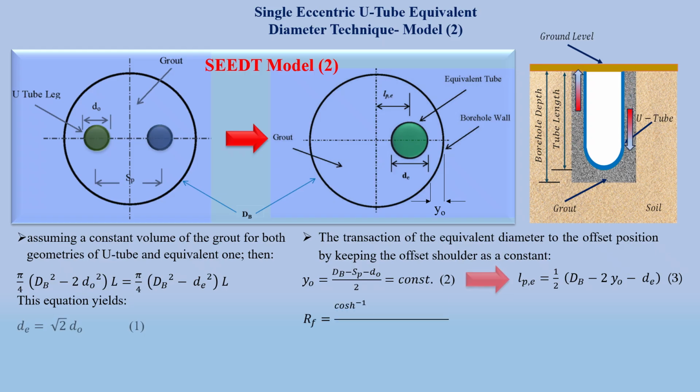And we will use the same equation which we have presented in previous correlations and episodes, that the thermal resistance of the grout material can be represented by the offset resistance for a tube or cylinder inside an external cylinder, for the shape representing the equivalent diameter.